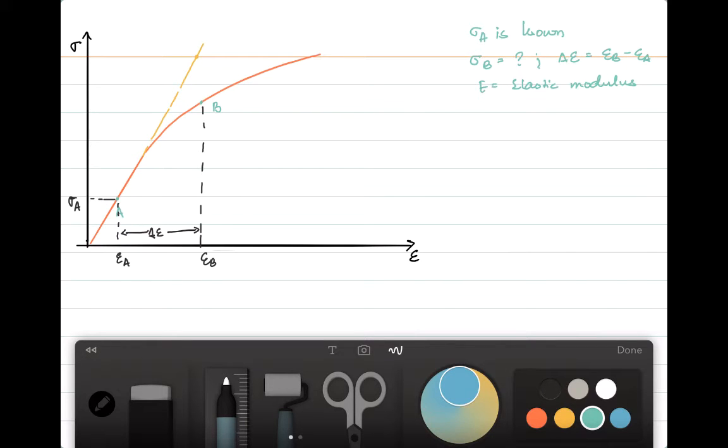Now let's say that with some material tests carried out, we already found out that there is a certain stress given as sigma Y, which corresponds to a point C, which defines yielding. These are some things that we already know. Now, let's apply a certain strain delta epsilon to this structure when it is at point A and try to find out what happens beyond this point. So we need to trace this curve, as I said before.